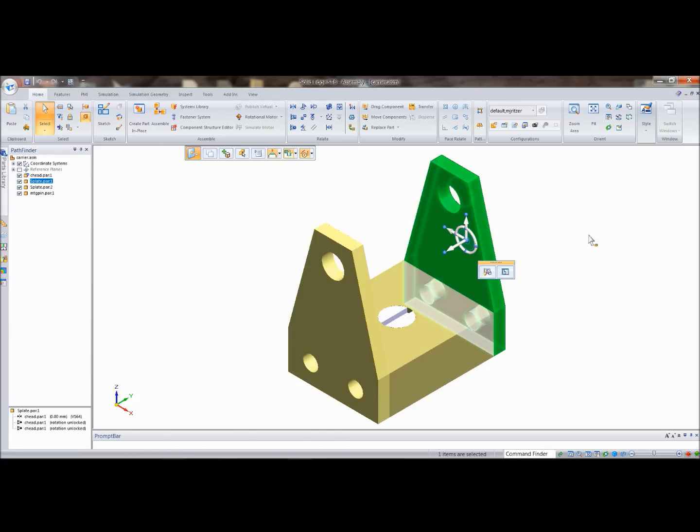And then also the reference plane inside here, the one that you can hold down Shift and you can change the order or the angle of the steering wheel, that's a little more apparent than it used to be in previous versions of Solid Edge. It was kind of hard to see that. So it's a little easier to see that reference plane in there. And again, by clicking, holding down the Shift key and clicking that center plane, you can get it to reorient the steering wheel on another plane. So these are all nice enhancements.